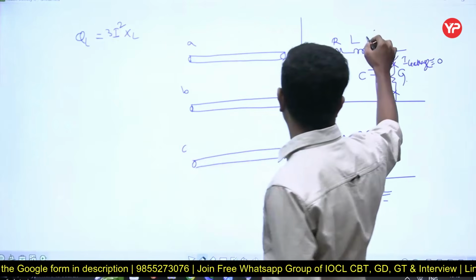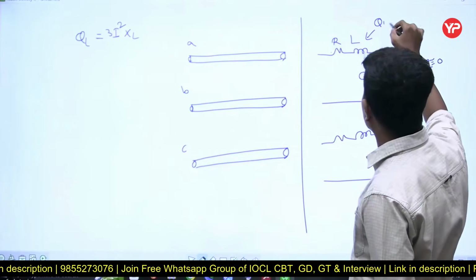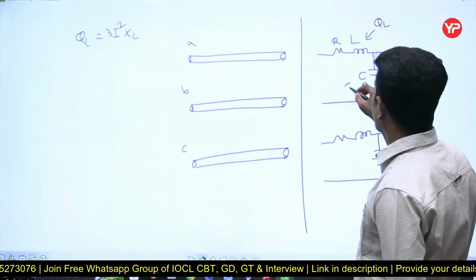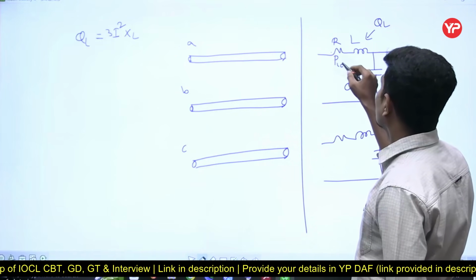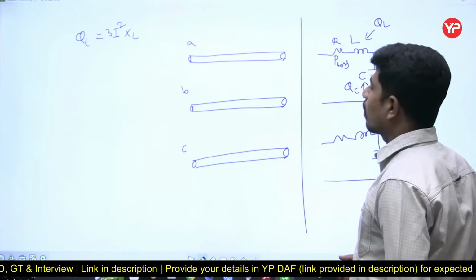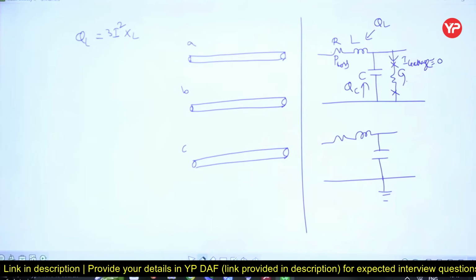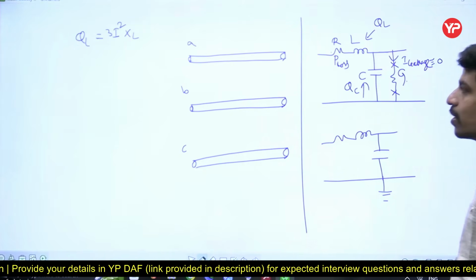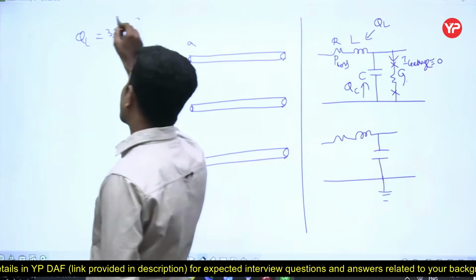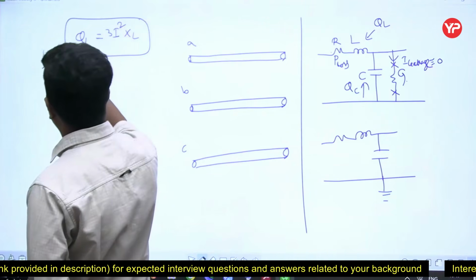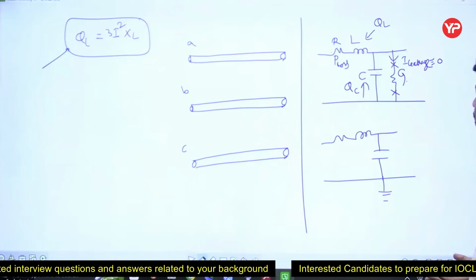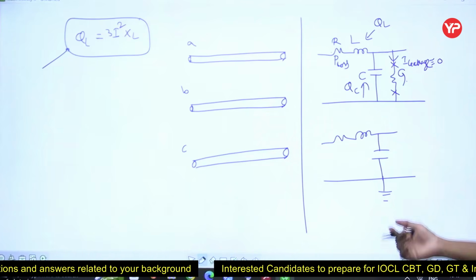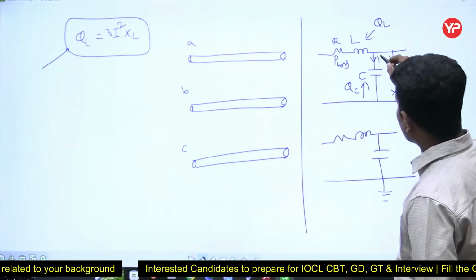So this is going to draw reactive power QL. This is going to supply reactive power QC. So this is going to have some power loss. Yeah, resistor always creates power loss. Now this is single phase equivalent circuit. For three phase, that's why these three become. Now this is 3 I square into XL. I told you in the last class that for transmission line, line current and phase current both are exactly the same. Clear? And this current is called as charging current.